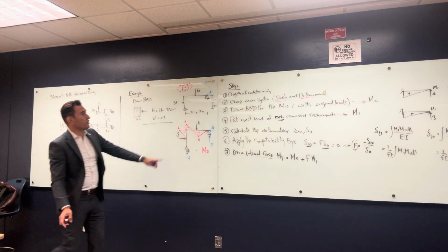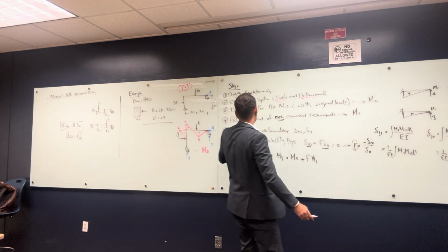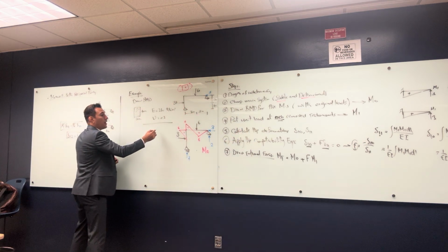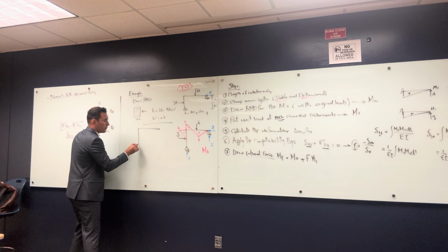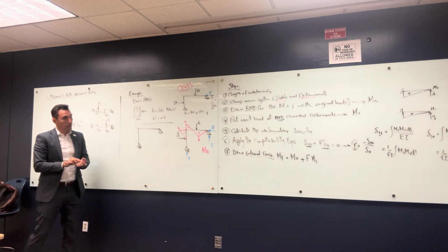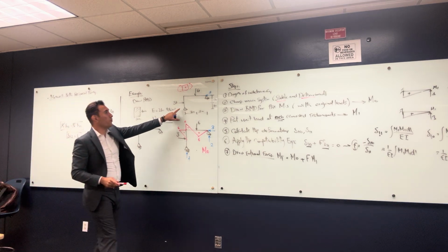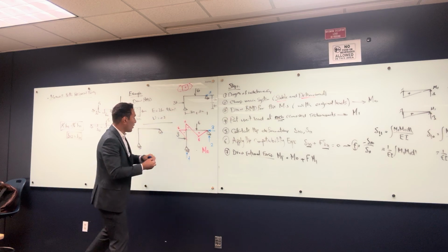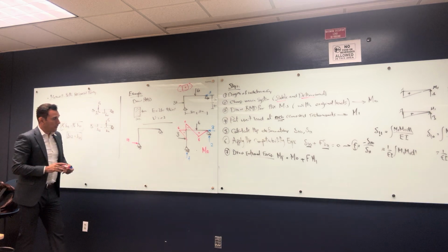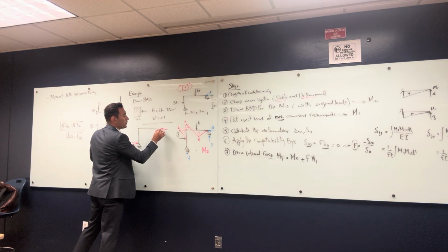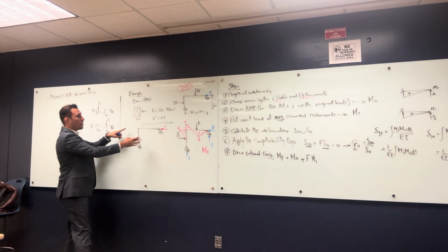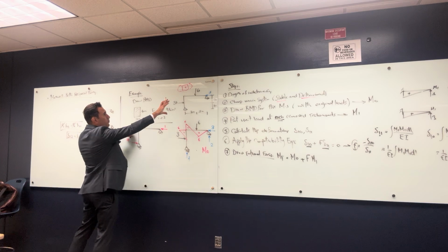Okay, so I finished this step, draw the bending moment diagram for the main system. Then step number 4, what should I do? What about that roller? I draw the same system again. I remove all the loads and then put a unit load where? At the roller, the removed redundant. I remove the horizontal force from here, so I'm going to put a unit load this way, a 1 ton unit load. When you put this 1 here, there's absolutely another 1 here, a reaction, and they both make a moment of 1 multiplied by arm 4.